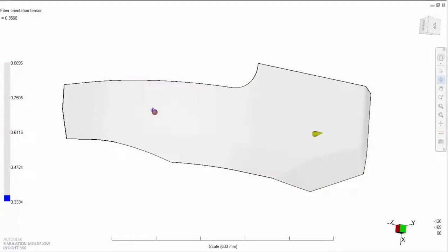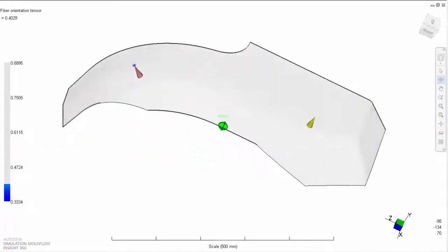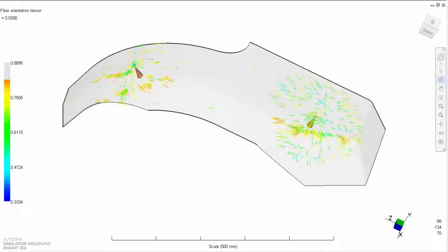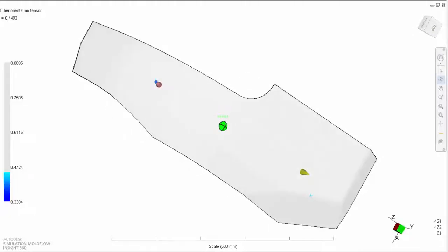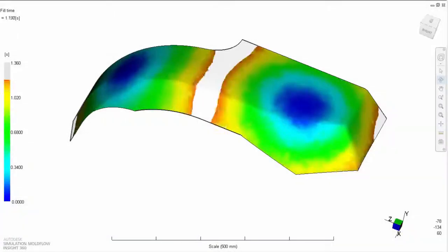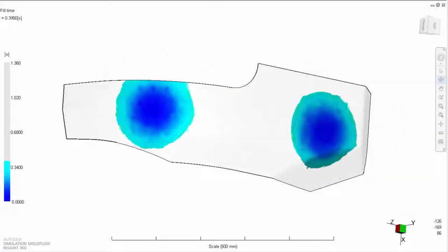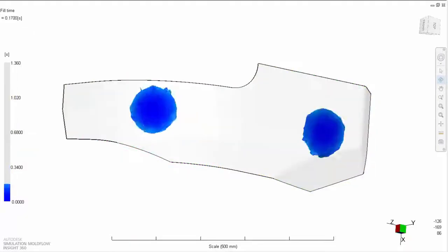In reality, fiber orientations are not perfectly random and can vary widely depending on the manufacturing method, such as gate locations. The impact on the structural analysis is twofold. One, fiber alignment causes orthotropic behavior of the material, which in turn changes the stiffness of the structure. Two, fiber alignment can cause weak areas of the structure where two flow fronts meet, which are known as weld lines.